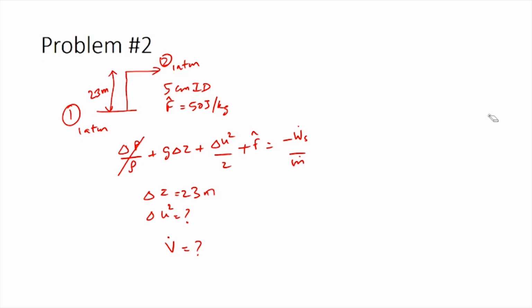As we already have assumed that the volumes are additive, we know the total volume of the final 60% mixture and the initial volume of the 95% glycerol mixture. So, we can calculate the volume of the 35% glycerol mixture using these two values. So, the volume of 35% glycerol mixture would be 2610 minus 1000, giving a value of 1610 liters. So, this is the volume which we are adding. We know that this is being added over a period of 13 minutes, from which we can calculate the volumetric flow rate. From the volumetric flow rate, we can calculate the linear velocity by dividing it by the cross sectional area. So, linear velocity at point 2 would be equal to